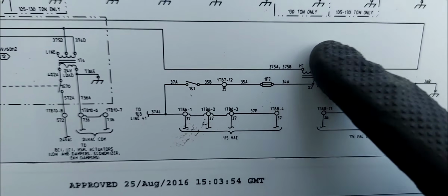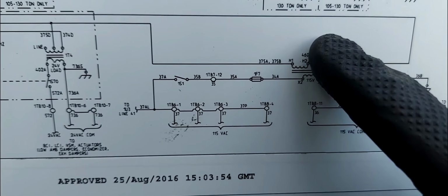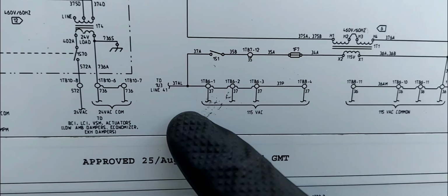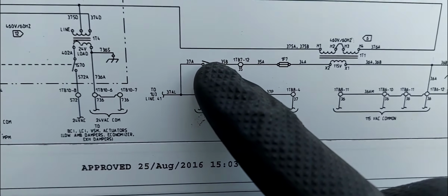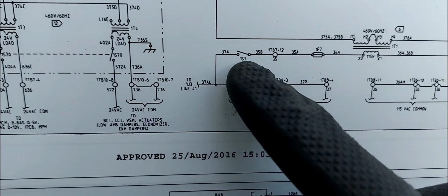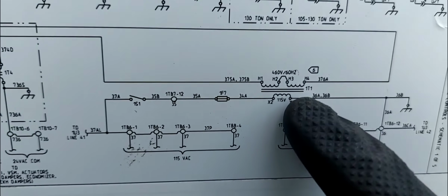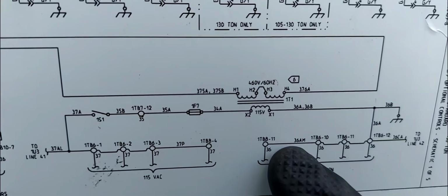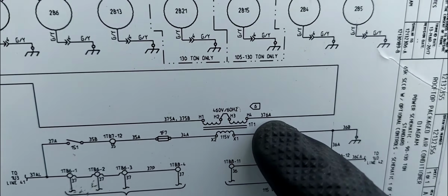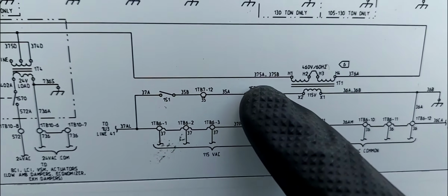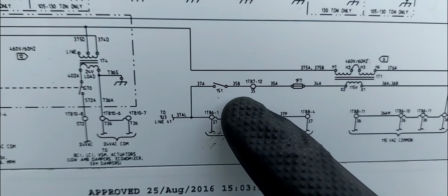That's line voltage up top. I mean, it's all line voltage. There's like 460 volts up here. You've got a fuse, and you've got this switch right here. If this switch is open, guys, you're going to end up getting an external stop as well. All right, so that's 1S1 and 1F7, and this transformer, is there a tag on it? I don't know. Oh yeah, there's a tag: 1T1. So let's go check this fuse right here, which is most likely the culprit, and then this switch right here, I'm sure it's on. Let's go double check that and grab my meter.